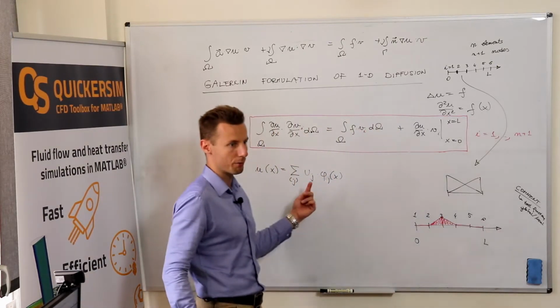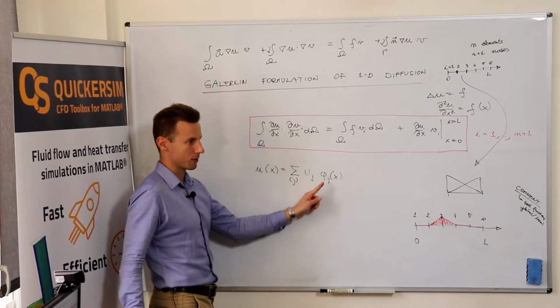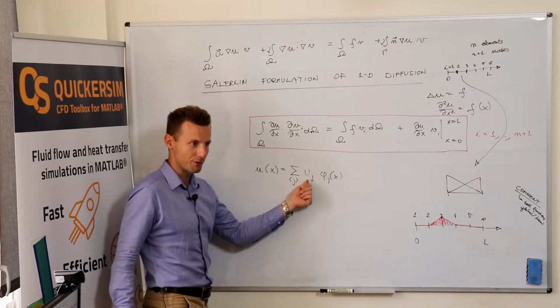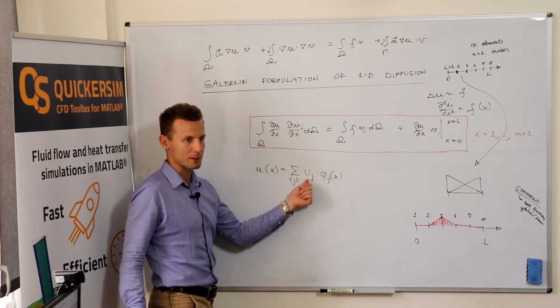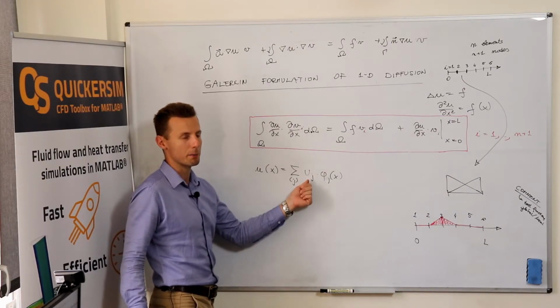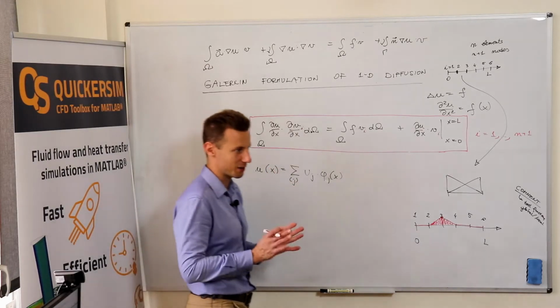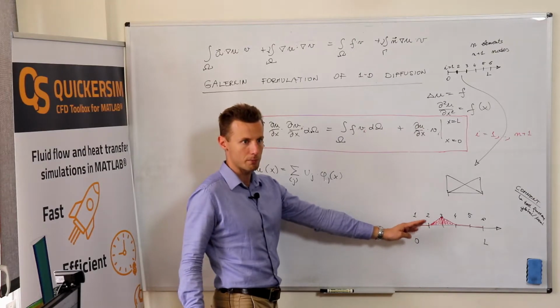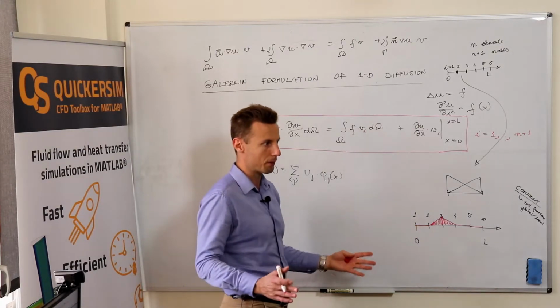The same applies for the shape functions. These functions represent the field. Very, very often, if you think about finite elements, you mainly are thinking about local shape functions inside one element. But for the sake of formulation, mathematically speaking, they are global functions.